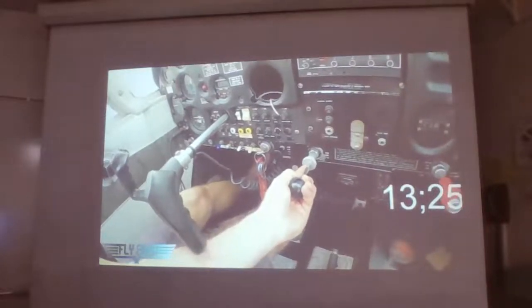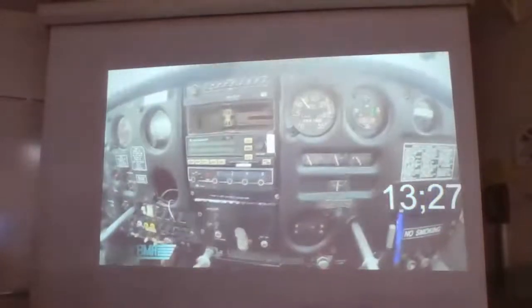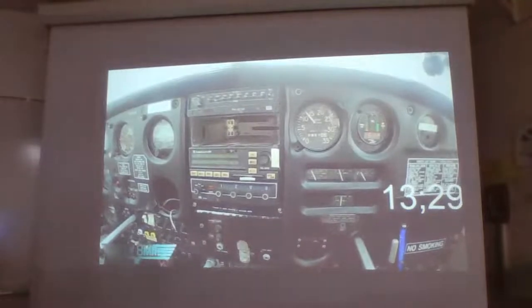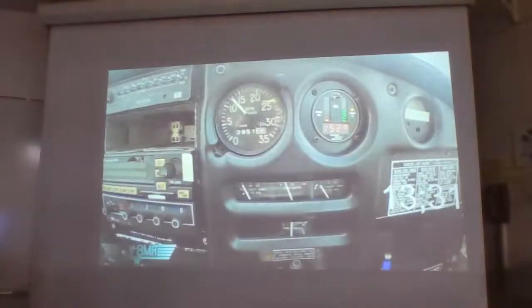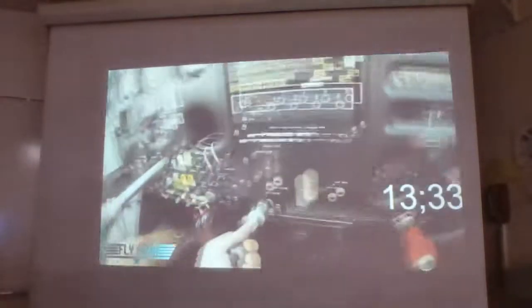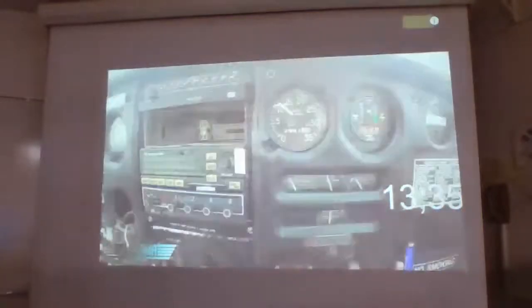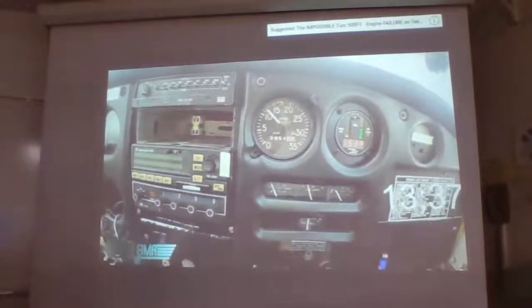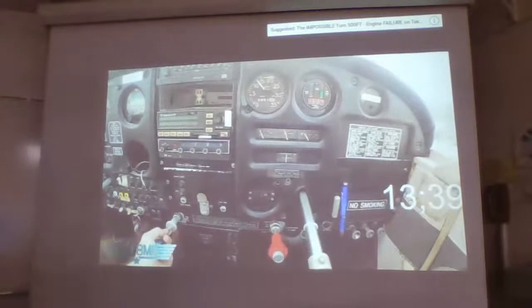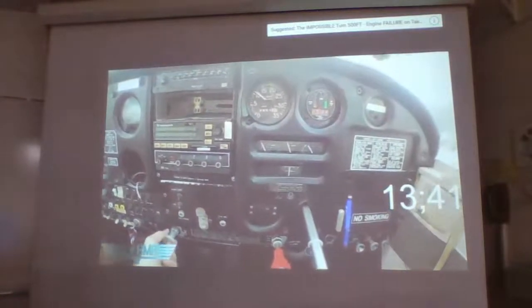It likes the throttle a little further closed because that's just too much air for it to breathe at such low RPM. So as you start losing that RPM in flight, it's really coming back on you. Maybe reducing the throttle actually gives you more power there. Try to feed in the throttle a little bit. That helps. See if we can catch and go a little higher.